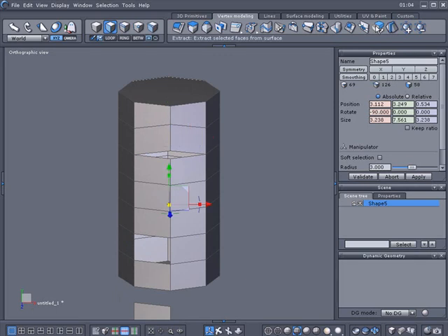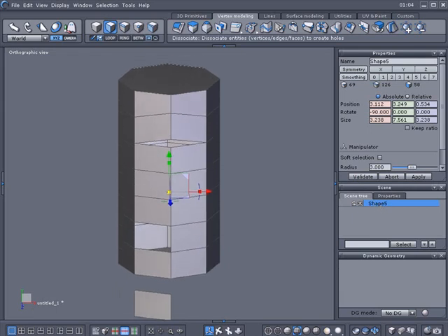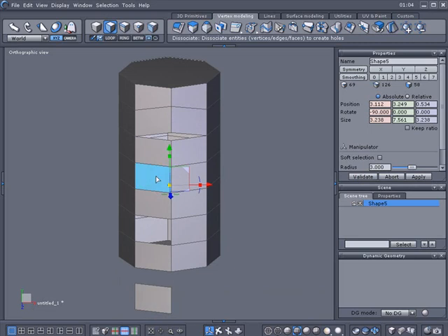We're going to use the extract here, and as you can see over here, I still got one object, and it appears that I got a face down here which is still part of this object. Now I'm going to use extract, and we're going to take a look over here in the scene properties. So I'll select the face, and we'll go up here and extract it. As you can see, now it has its own form over here in the scene tree.